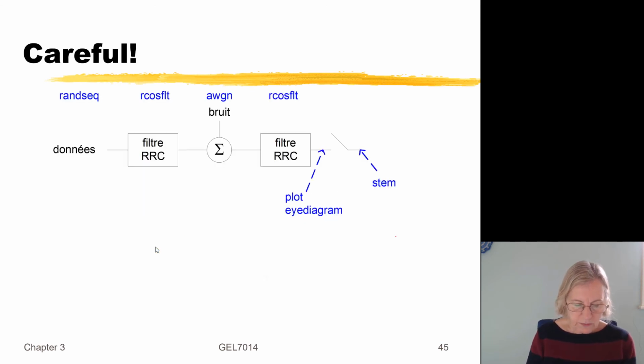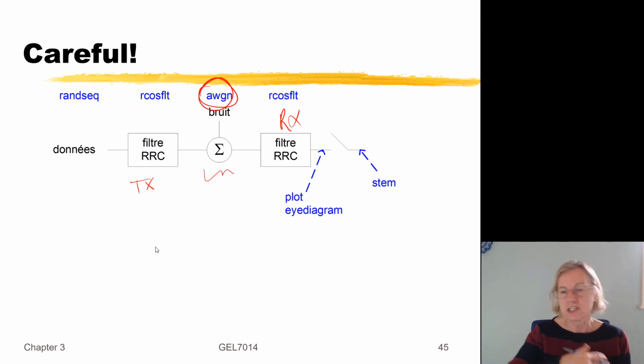So normally when you have your transmit and your receiver, you would add noise in between them. And as I mentioned earlier, that would have additive white Gaussian noise, which is infinite bandwidth, and the filter limits the amount of noise power, which actually is coming into play.